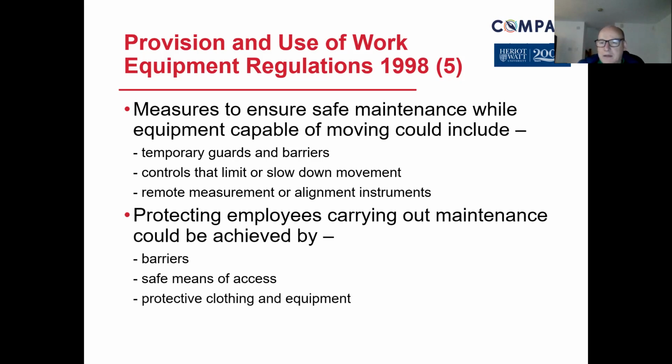That always reminds me of the bad incident where people in a bakery died. Two maintenance engineers were burnt to death because they didn't allow a good 24 hours for the oven to cool down. And for some reason, there was a one-way system. So you could go in, but you couldn't go out the same way. You had to walk through the center of the oven in order to get out the other side. I don't know what was going on there, but it meant that they walked to their death because it was too hot. By the time they got to the center of the oven, they were overcome and heat exhausted, and then they cooked, basically. So again, think about getting in and getting out.